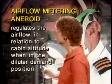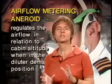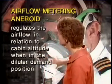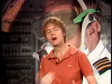So what it's got is an aneroid in the demand valve here, and what that does is it senses the outside pressure, and then it allows a certain amount of ambient outside air to come in when you breathe on the oxygen so that you get some oxygen and some outside air, and the amount of outside air is reduced and the amount of oxygen from the mask is increased as you go to a higher and higher altitude. So that aneroid regulates the airflow, the ambient airflow, in relation to cabin altitude when it's in the diluter demand position.